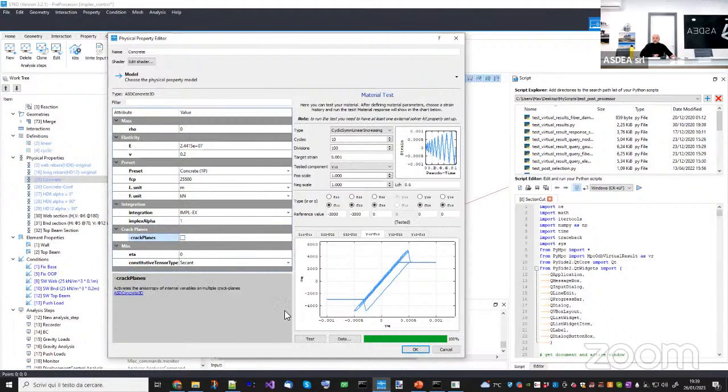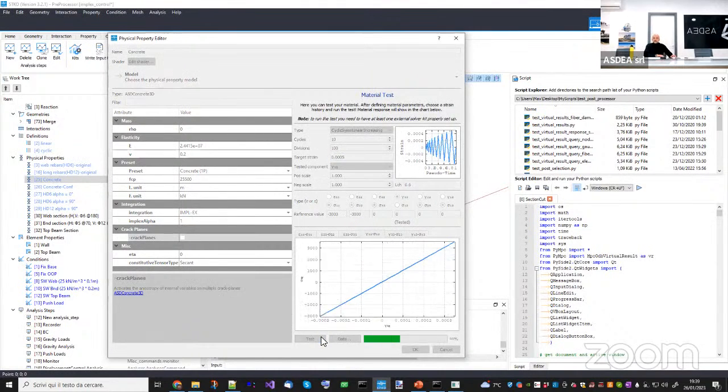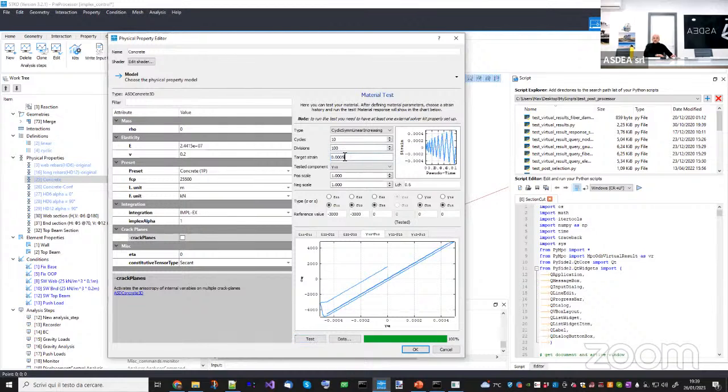If you remember, if I switch off the crack planes, you see, I will not reach the point here. Let me push it a little bit less. Okay. No, that was fine. Here I was loading up to 4.5 megapascal, then I go down, I have softening, I go here, and I have the same damage. So this one is an isotropic damage.